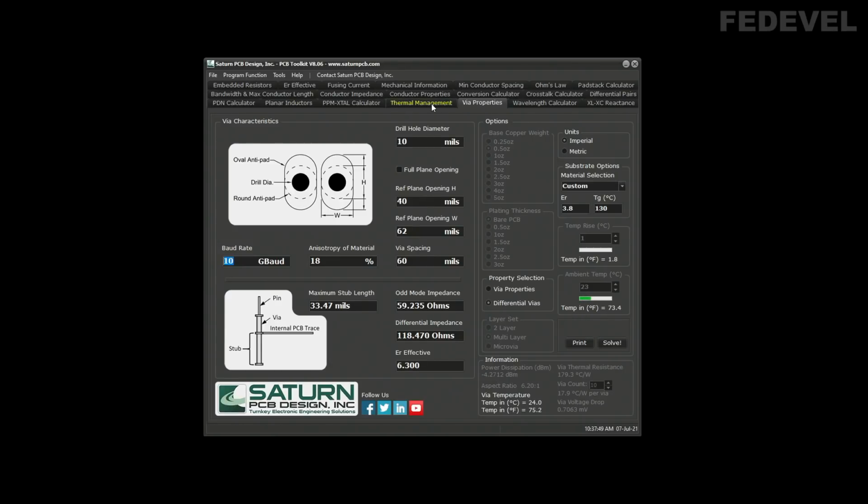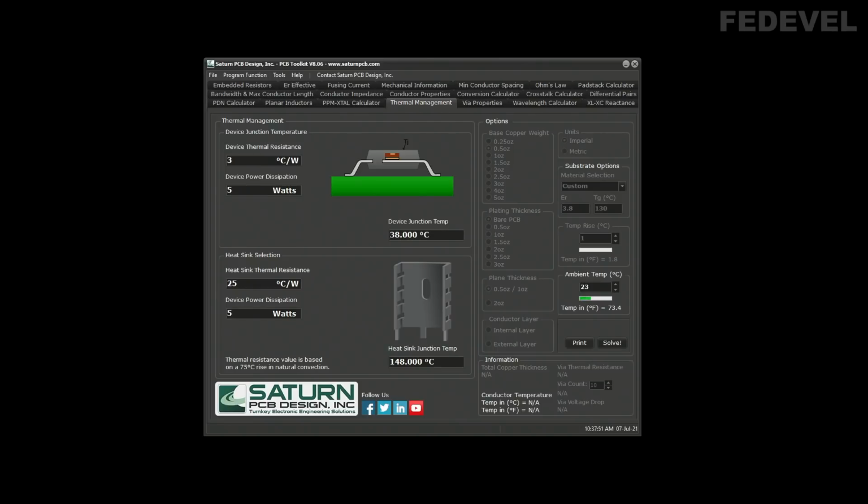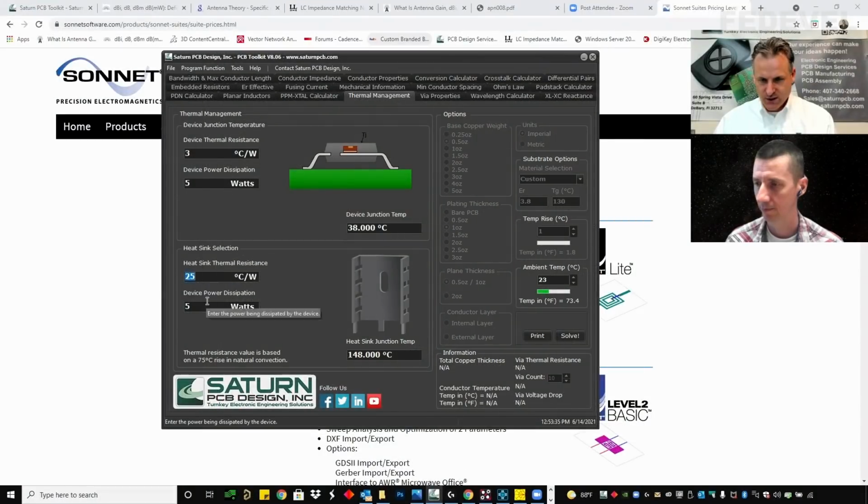Yeah, I use this once in a while for heat sinks. Basically it tells you how good or bad your heat sink is, if your heat sink will be able to drop your part enough degrees C to handle it. Your part will be rated in a certain wattage.